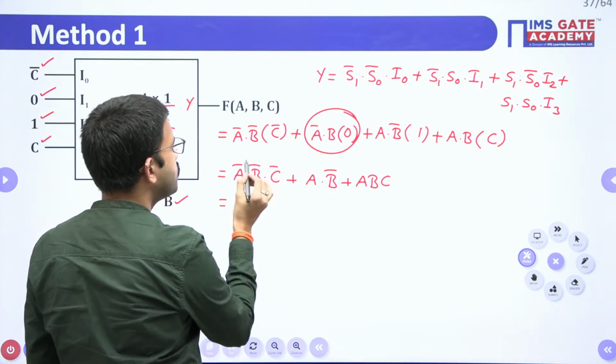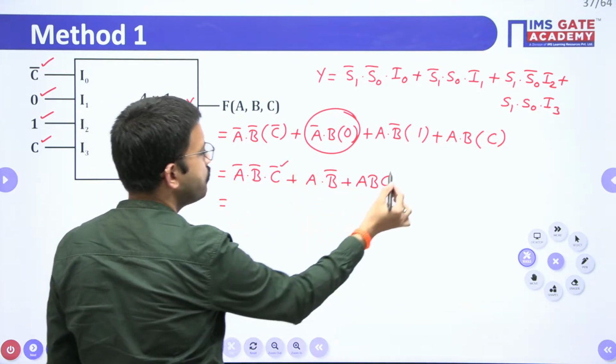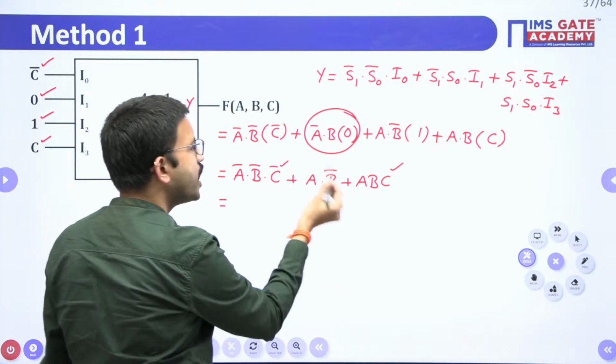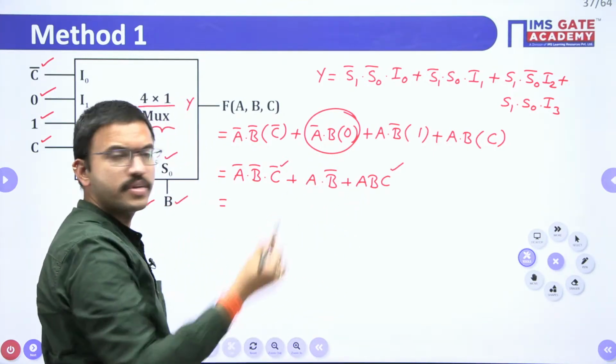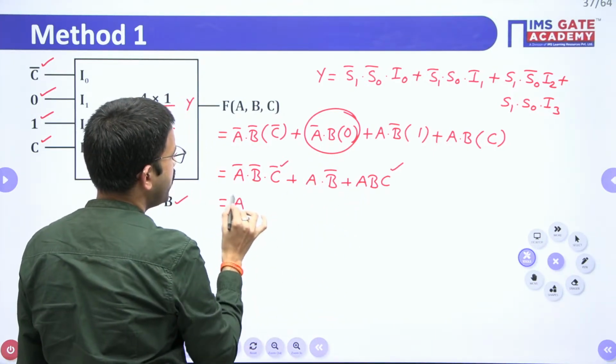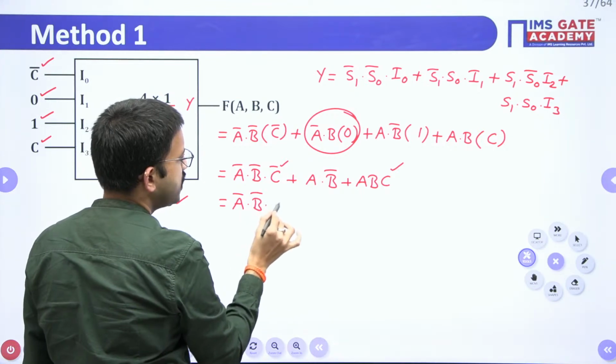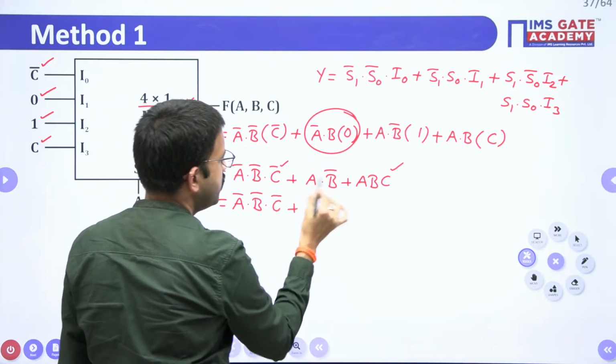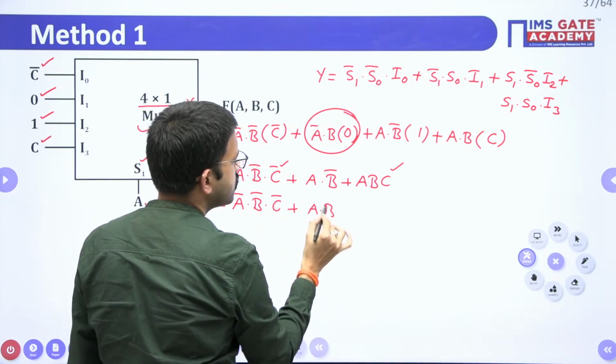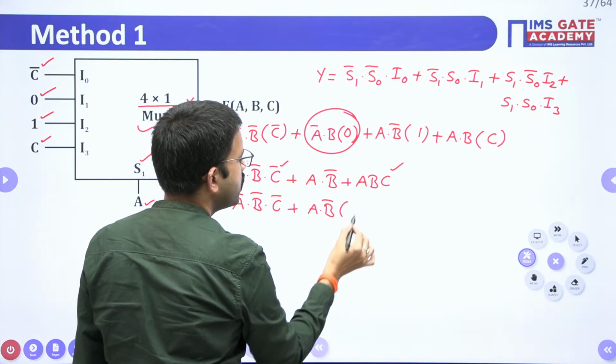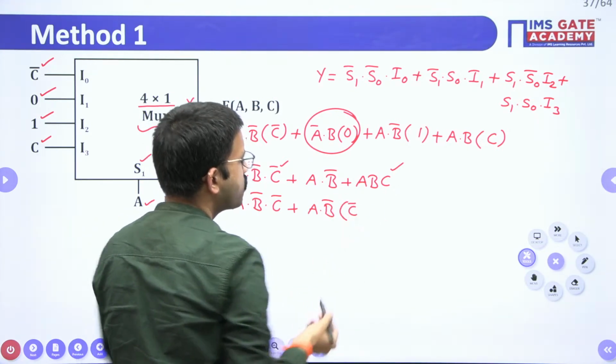If you observe, you are having min terms in the choices, and here also. So for the time being, let us convert this one also into min term form. A bar B bar C bar I am copying as it is. Here you are having A B bar. You can multiply with 1, the equivalent value will remain the same.